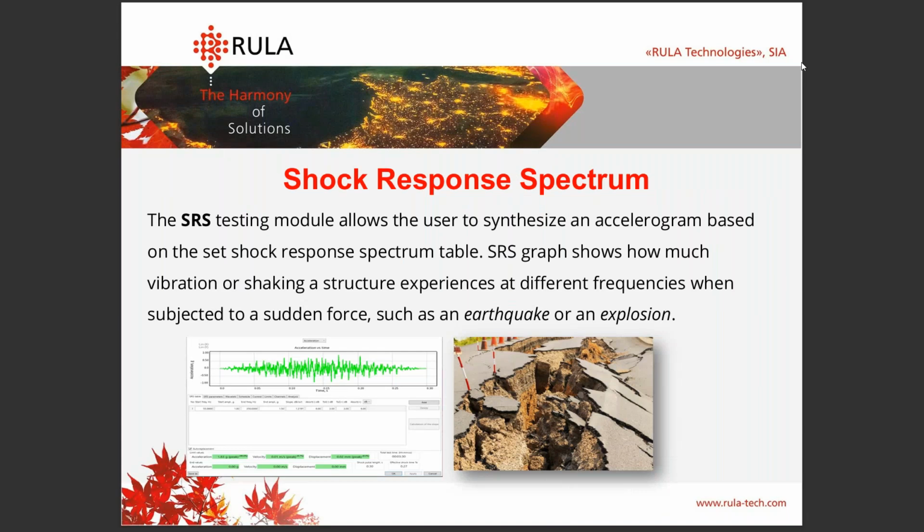It aims to produce and excite several different oscillations and resonance frequencies inside the device under test. These calculations can follow an arbitrary list of frequencies, but usually a certain n-octave range is taken for this purpose, so third octave, quarter octave, etc., depending on the technical task.